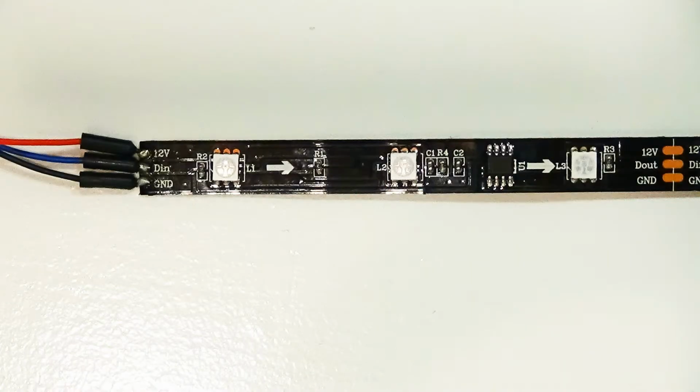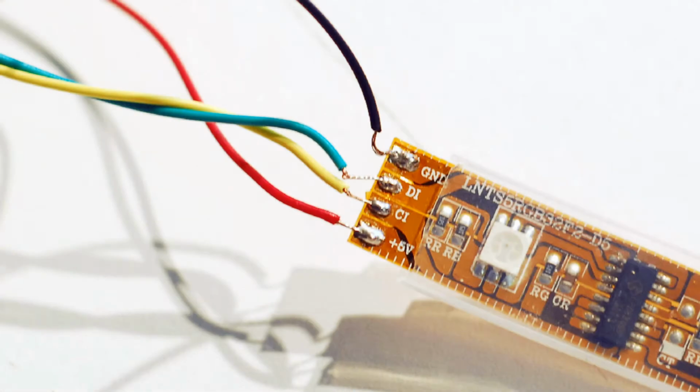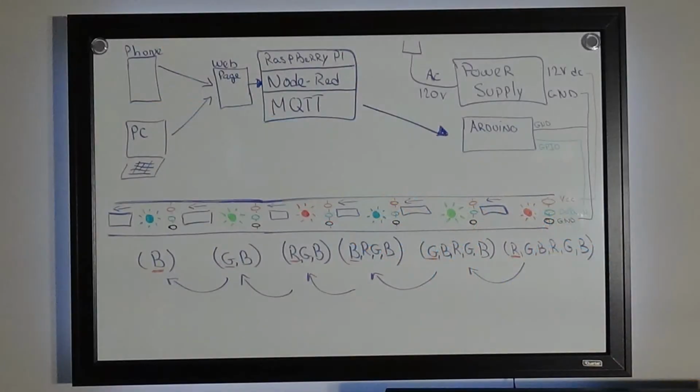The programmable LEDs have one extra component, an interface that controls one or more LEDs. One or two additional terminals appear, which are used to communicate information to the controller: the data, and sometimes also a clock. Although the connectors that carry the power supply are connected in parallel, the data is transmitted in series, and this makes them individually programmable. The data signal goes from one controller to another.